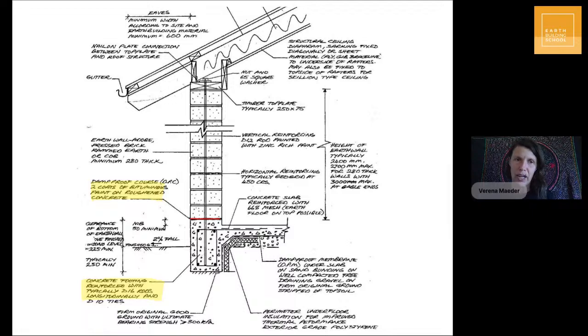Mud when it's dry, in its dry form, is very, very dry. So it would be continuously wicking moisture out of the foundation. So that's why you have to apply this damp-proof course. And usually it is a thing like bitumen paint or something like that. Yeah, so you have this damp-proof course, which is a very important part of the foundation.